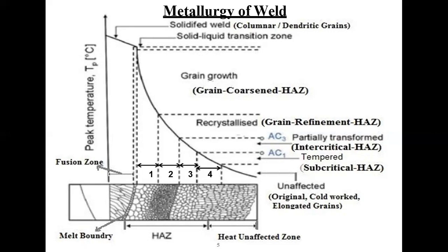When we take the temperatures, in case of this side or these sides, these are the cooler sections with respect to this. When the temperature is released from the heating zone, we can see this type of curve, and the liquid portion of the molten metal will be converted into the solid section.